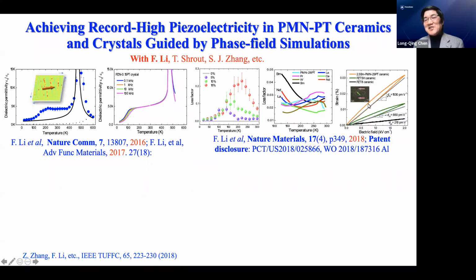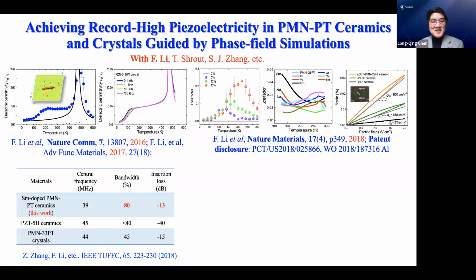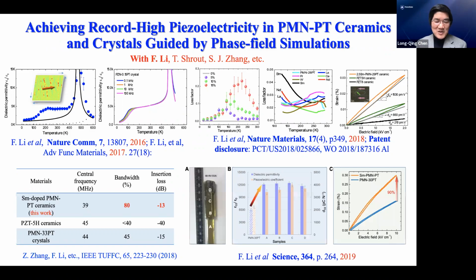Indeed, using samarium doping, we were able to dramatically increase the piezoelectric response of PMN-PT ceramics with just a little bit of doping, and it was tested in needle-shaped transducers with much better performance. Later this samarium-doped PMN-PT chemistry was also used to grow single crystals, and we were able to almost double, a 90% increase over the piezoelectric response achieved about 20 years ago here at Penn State.